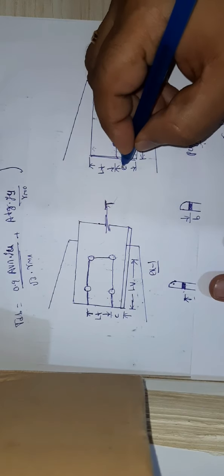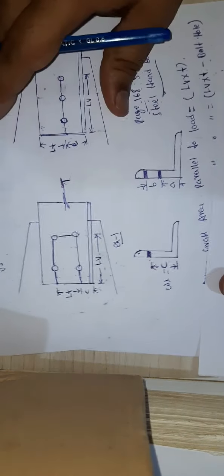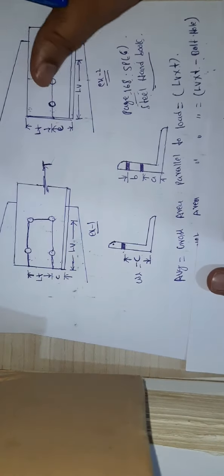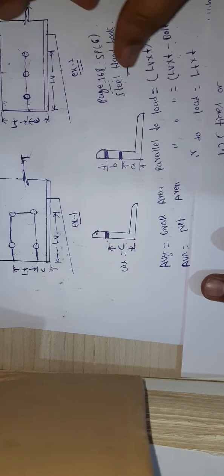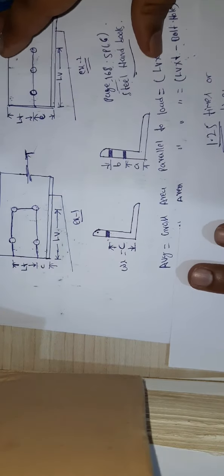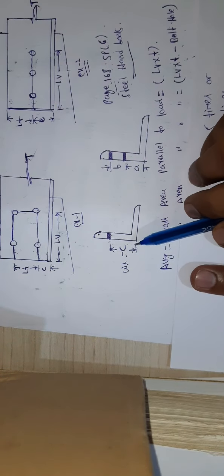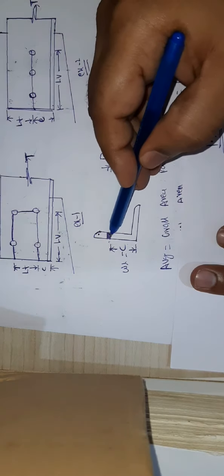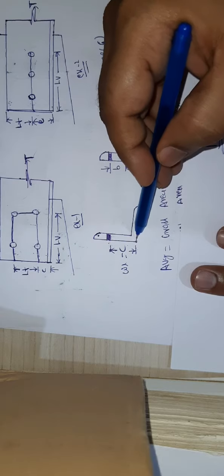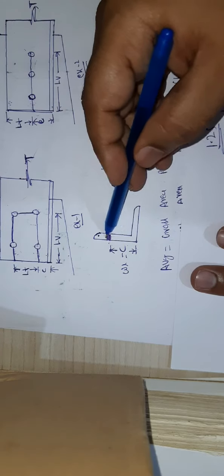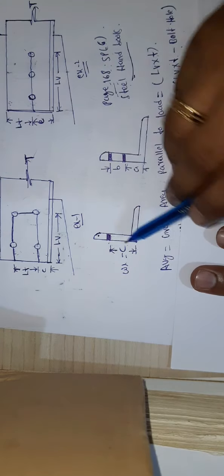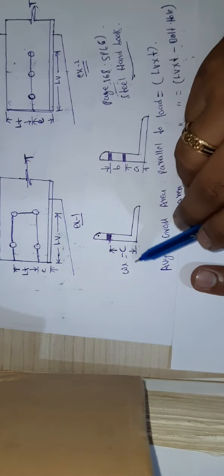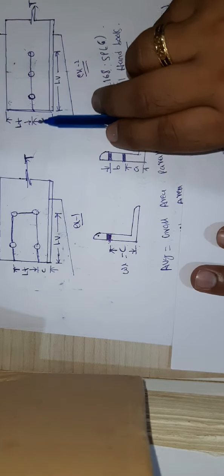This is C. What is C? Or WL? Maybe in the second mode of failure, failure due to rupture, I explained what WL is. W means the distance from the first bolt line to the bottom of the connected leg. That distance between the first bolt line and the bottom of the connected leg is taken as WL, that is C. So there is C here.